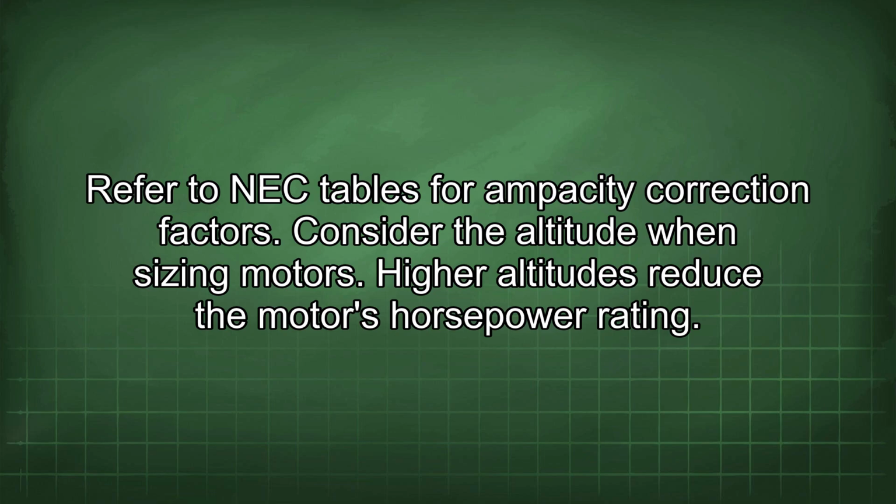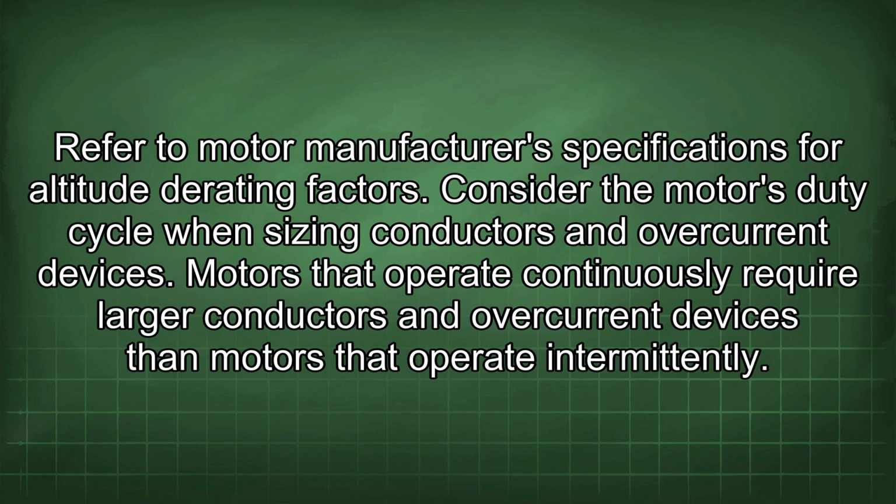Consider the altitude when sizing motors. Higher altitudes reduce the motor's horsepower rating. Refer to motor manufacturer's specifications for altitude rating factors.